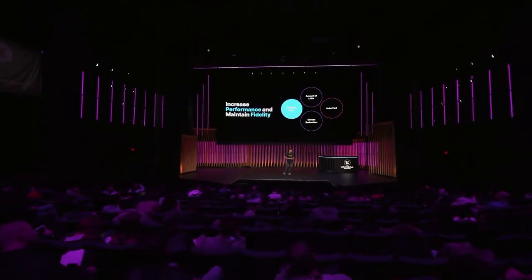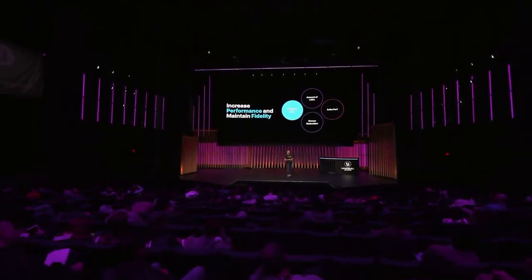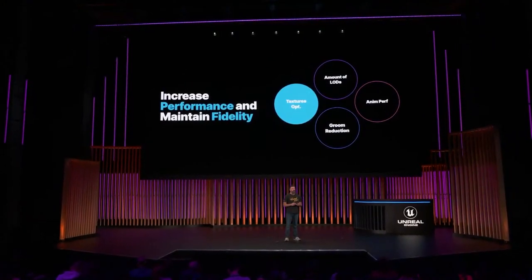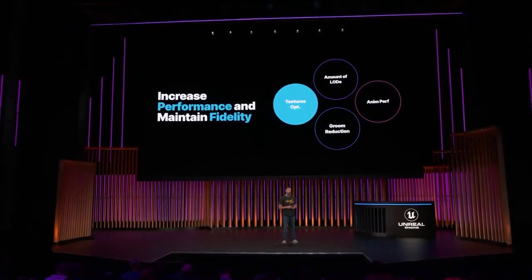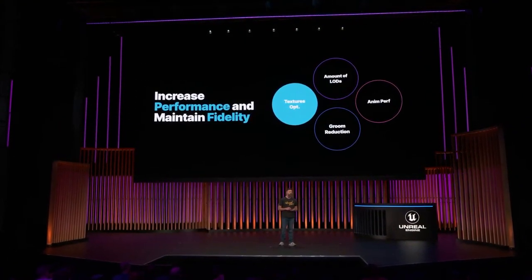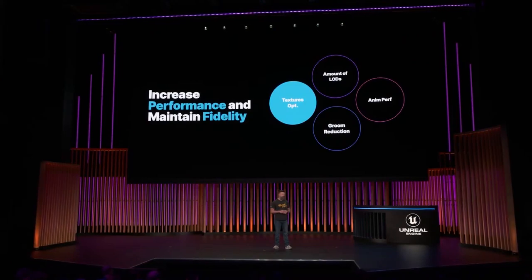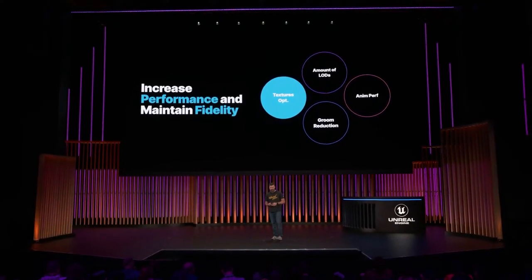One of the areas that we thought we could make some of the most improvements was on the material and texture side of things. Through baking textures, shader-based material efficiencies, simplifying operations, and fewer instructions, we were able to reduce the material and texture size by quite a lot. Our look dev artists put a lot of time and effort into making sure the metahumans retain as much of the high visual fidelity that their Unreal counterparts have, but in a significantly smaller size. Now let's take a look at some of the details here.